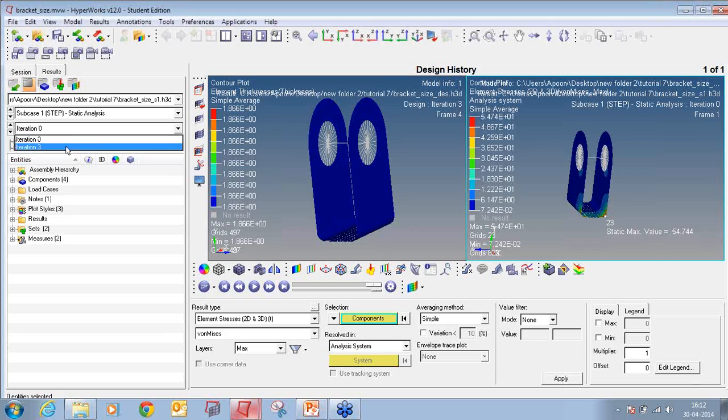So for this particular component, I am allowed to get some higher values of stresses. But I want to reduce the thickness of the component so that the cost of the component will decrease. So by reducing the thickness, it will increase the stress, but my allowable stress is 100. So I am getting the stress lower than 100, which is 88, and thickness is changed drastically to 0.7 mm approximately, which is a big thing.